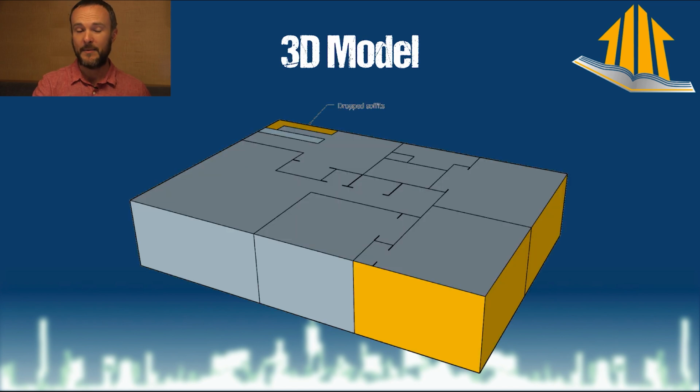So here's the 3D model that I mentioned. You're going to have to know the ceiling area of each room, the wall area of each room, the floor area of each room. And all you're paying attention to is the enclosure itself. I do not care about interior walls because it's what's called adiabatic, which means that it's the same temperature on both sides. It's that delta T issue that we were talking about earlier. All you are doing with the software is trying to figure out how much heat is bleeding out of or into your enclosure. You don't have to model interior anything.